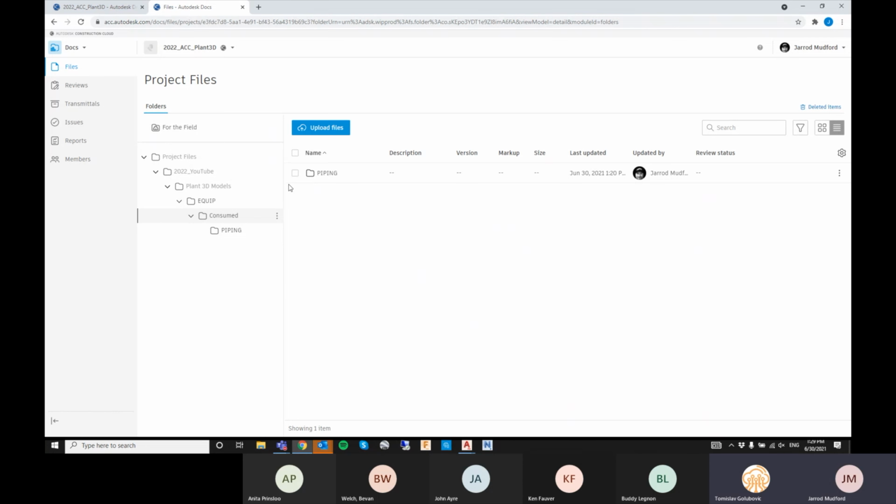But why would we not use Navisworks and just give it to them in an NWD file on a nightly basis? I don't know. So let's say they don't have any Autodesk software at all other than ACC. But then I guess you're going to give them NWDs using Navisworks Freedom. Yeah, Freedom Viewer, it's free. So they can download those, and the majority of my clients all know how to use it, and that's what they're expecting.